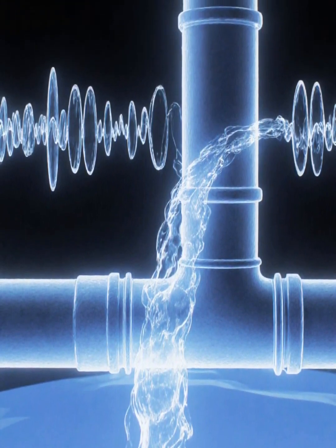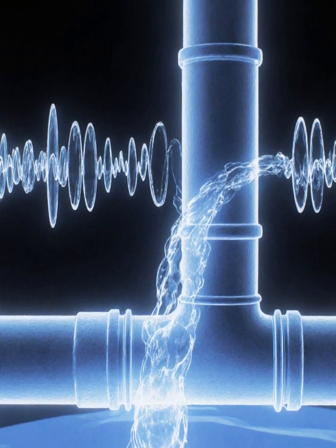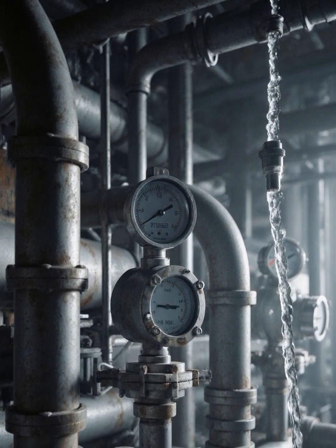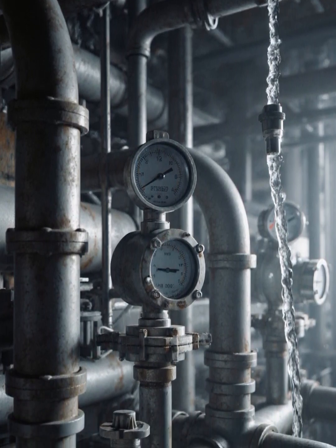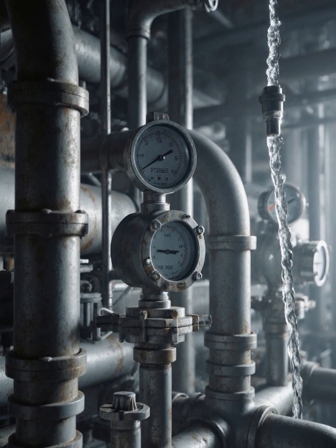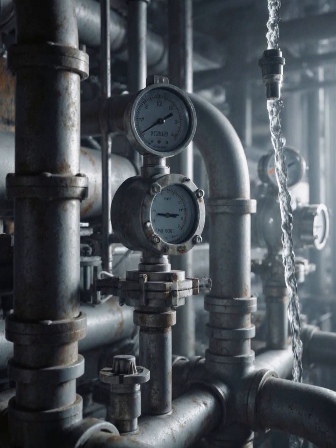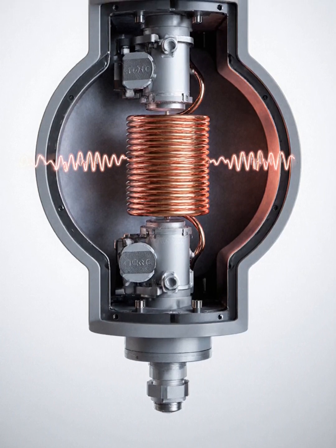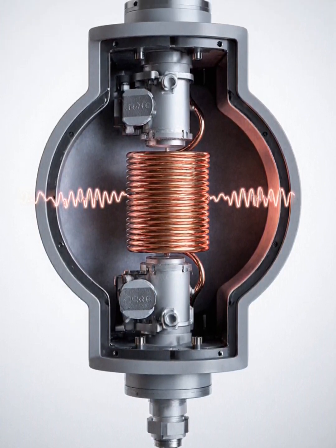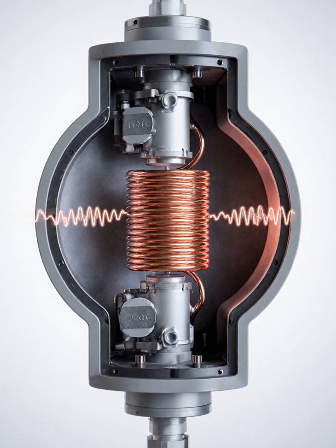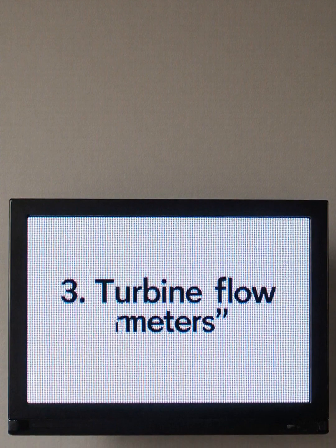The induced voltage is not affected by the physical properties of liquids like temperature, viscosity, pressure, density, and conductivity, as long as the conductivity of the measured liquid is above the minimum threshold level. For reliable measurement, the pipe must be completely full of liquid. The electromagnetic field coil assembly is excited by pulsed DC technique, which eliminates the interfering noise and provides automatic zero correction. 3. Turbine flow meters.